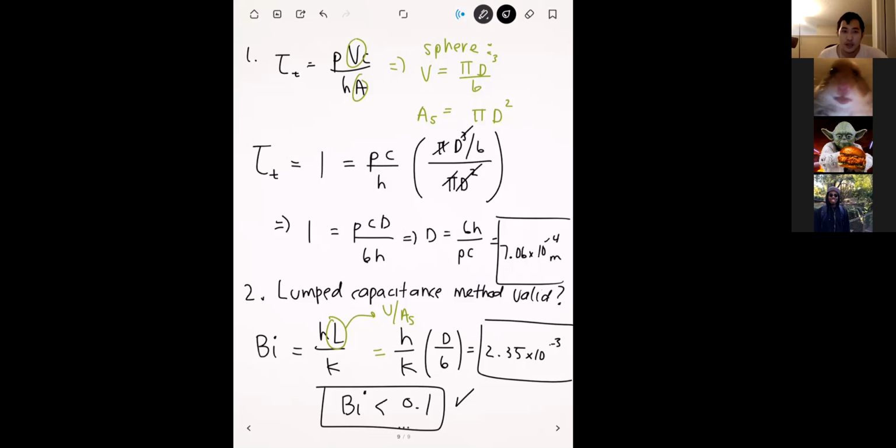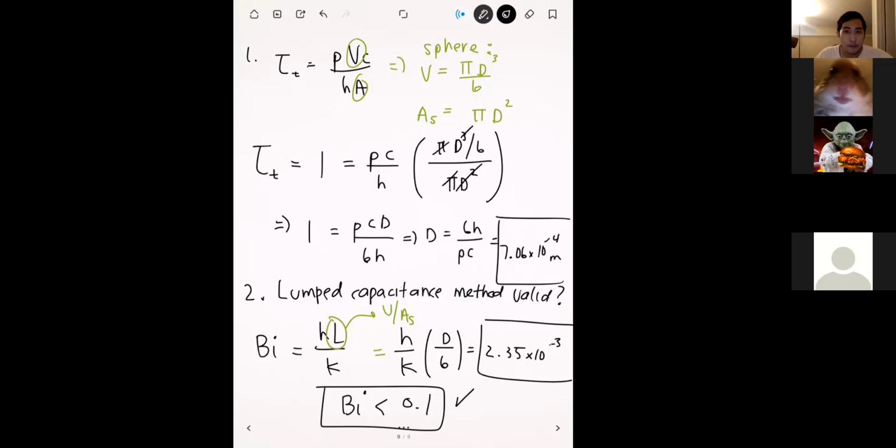All the Biot number says is that you have h times length divided by k. In the worst case scenario, and I'll say this is fairly safe to do in a lot of situations, for L you can just take the ratio of the volume and surface area, and that's what you plug in. Oh, thank you. Professor? Yep. Let's say it was an I beam. Would we then just do volume over area again? Yep. This volume over area approach works for most objects.